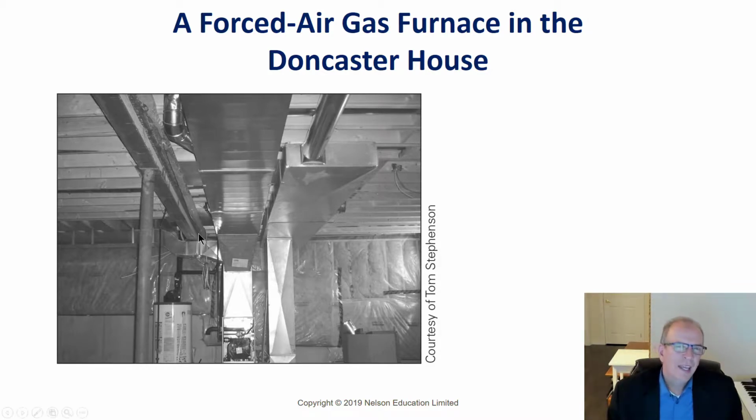It's why it doesn't take care of physics so easily when you've got the air conditioner in the summer, because now you've got cool air coming off the top and warm air coming down the bottom. And it's harder to get that cool air up to the second floor. Some of you, if you've lived in a 2-story house with air conditioning, may find that on hot days the air conditioner is not powerful enough to get that cool air upstairs, or you have to keep the first floor really cool in order to get the second floor reasonably cool. But in the winter, it works quite fine.